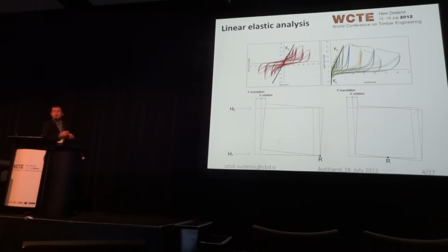And there's a difference. Even if you use a substitute stiffness for tension and a substitute stiffness for compression, they are different. So if you want to model the connections with linear connectors, so basically with springs, you have to use bilinear elements. But bilinear elements cannot be used in the modal analysis, because you have to have one single matrix, therefore you have to have one single stiffness.